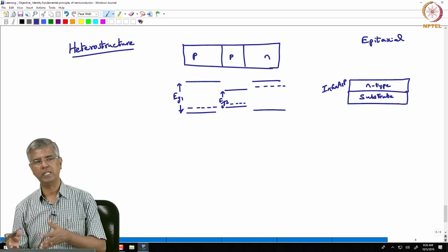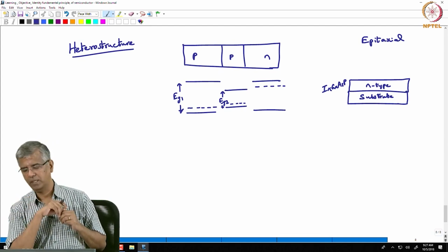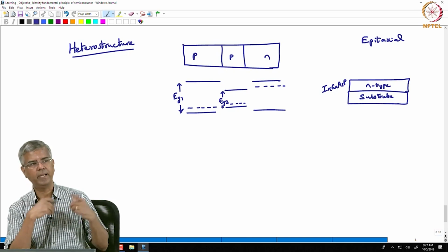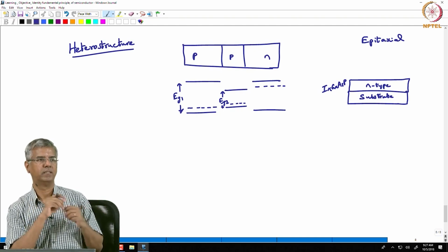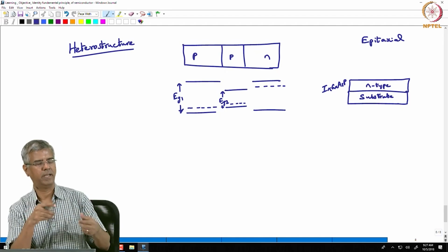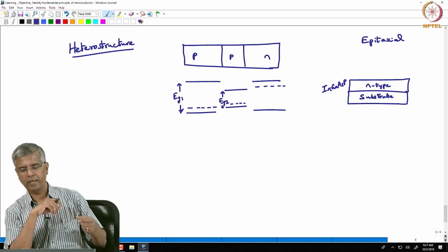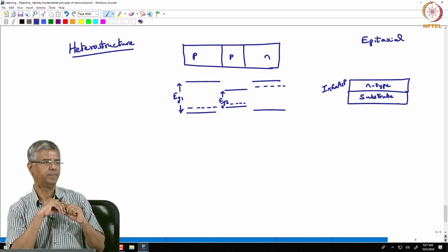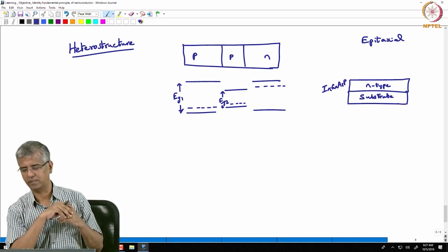Okay. So you initially start depositing indium gallium arsenide phosphide to make that n-type layer, and then you change the gallium and arsenic concentrations, and of course the corresponding dopants also, and then you get a p-type layer, but with a different band gap energy. Okay, the proportions we are not going into the details, but that's just the idea, right.